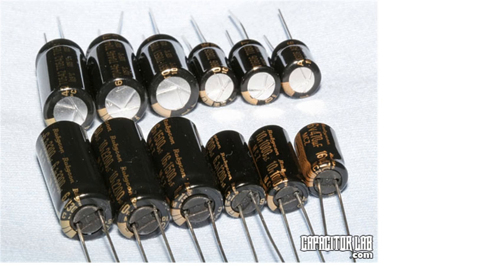Very simple idea, storing charge. But the applications for this are very wide and can be used in a lot of different things. These are some common examples of the capacitors that you might find in a computer or in an electrical device. These are cylindrical capacitors, and to make these they've taken the parallel plates, made those plates into foil, and put a piece of paper in between the two plates as the dielectric, and rolled it up into a cylinder, and then they attach the leads onto those foil pieces.